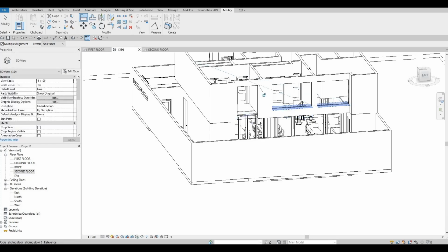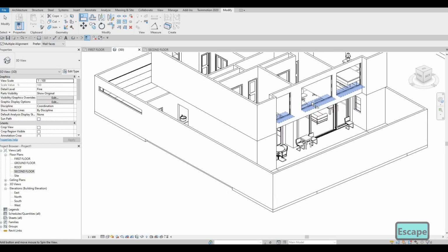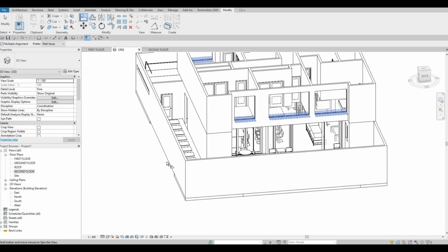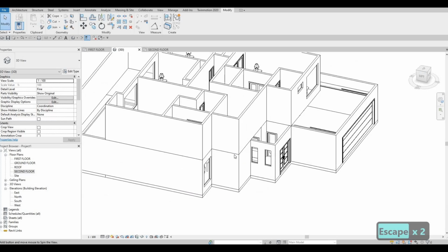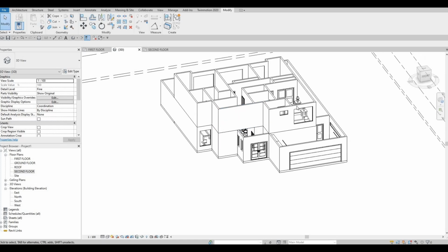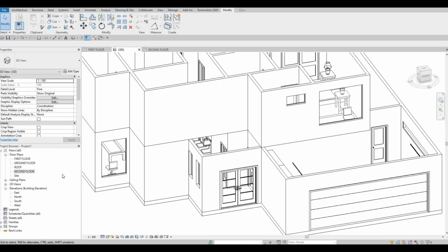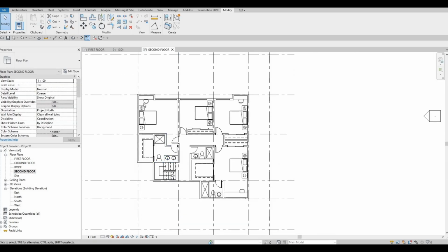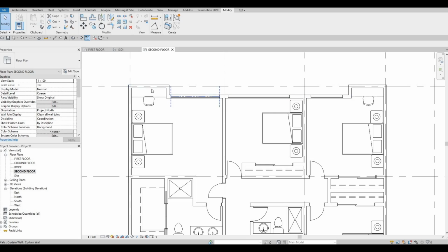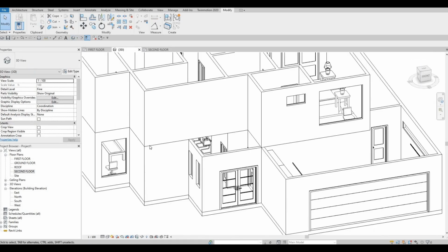We don't have any balcony, that's why I'm pulling it up like so. If we have a balcony, we need to pull it down onto the floor. So we're going to add the grid lines later on, so curtain grids, and then the mullions afterwards. So now what we're gonna do is we're gonna add in a floor, and that floor will be around the interior part of the wall. It's because I don't want that one to be shown around here.